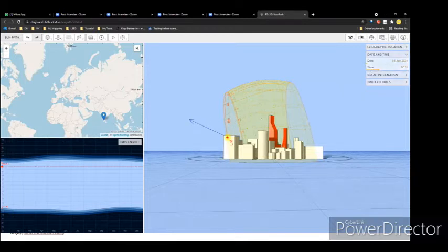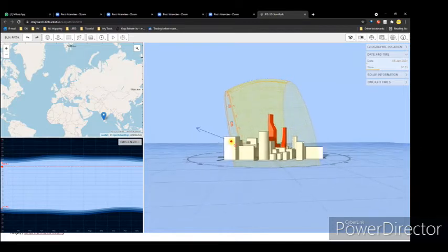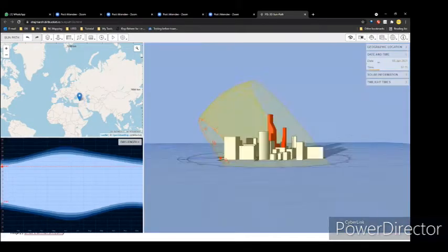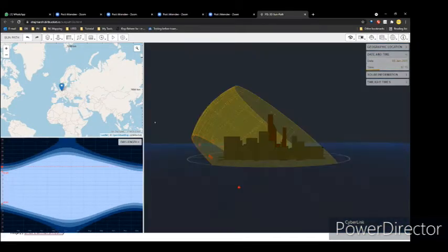So there is no point in saying that during the December month we are going to let in more light. In nature, you have to cut down radiation from the sun, irrespective of whether it's summer or winter. So you have to design your shading systems or glass percentages accordingly. But this is not common in the Netherlands. You see over here why winter sun is very important.